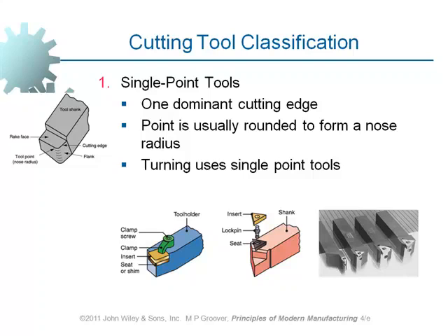And sometimes the quality of high-speed steels is no good for taking the cut from harder materials. For those type of materials, we've got to make use of carbide inserts. As you can see here, there is a shank which is used in the tool holder, and there is an insert, as I said, which is placed at the tip of the cutting tool. And there are different shapes of the inserts for different types of geometries and also for different materials. And we can insert the right material.